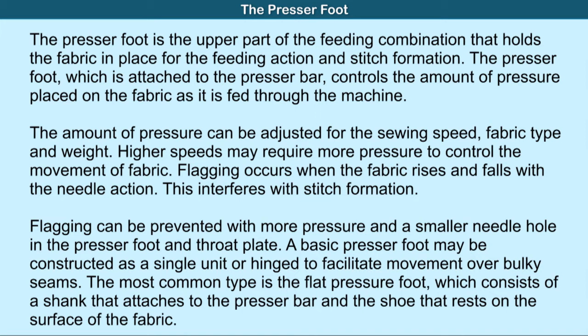Flagging occurs when the fabric rises and falls with the needle action. This interferes with stitch formation.